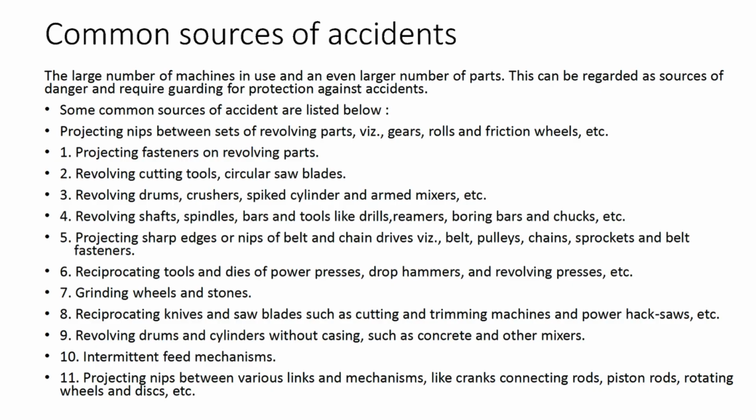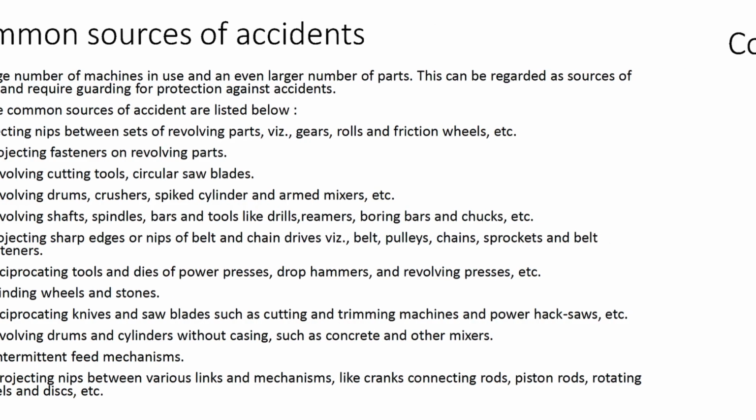projecting sharp edges or nips of belt and chain drives like belt pulleys, chains, sprockets, and belt fasteners, reciprocating tools and dies of power presses, drop hammers, and revolving presses, grinding wheels and stones, reciprocating knives and saw blades such as in power hacksaws, revolving drums and cylinders without casing, like concrete mixers, intermittent feed mechanisms, and projecting nips between various links and mechanisms, like cranks, connecting rods, piston rods, and rotating wheels and discs.